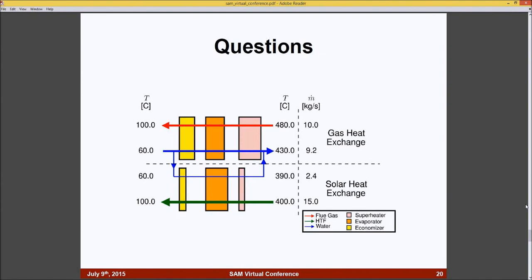A few slides from the end, you showed the gas turbine output without solar contribution as a constant output. I'm sure you know that typically that value fluctuates as the ambient temperature changes, with high ambient temperatures resulting in a decreased output. A lot of the benefit people claim hybridization will allow is for that solar contribution to be highest when the gas turbine output is lowest. I'm curious if that's something you plan on looking at a little later as your optimization process goes on.